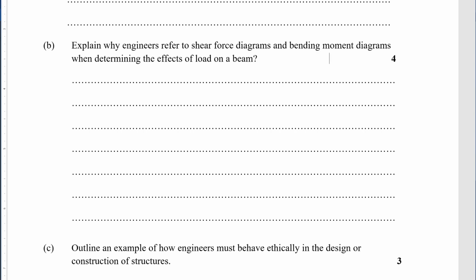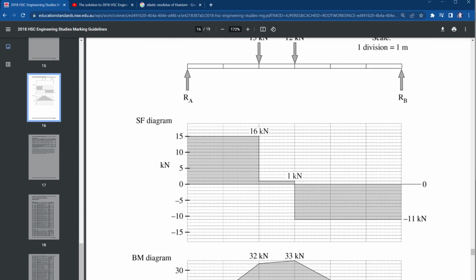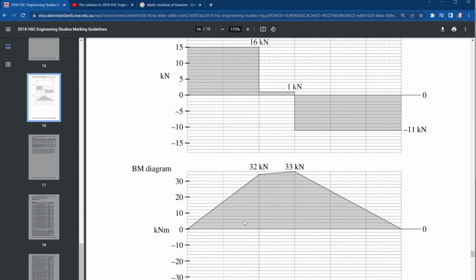So a concrete beam typically won't have the same reinforcing all the way through. It'll have more reinforcement at the higher bending moments and less elsewhere, so it might have double the reinforcing here compared to throughout the whole beam. So you might design the concrete beam for enough steel to take 16 kilonewton meters.